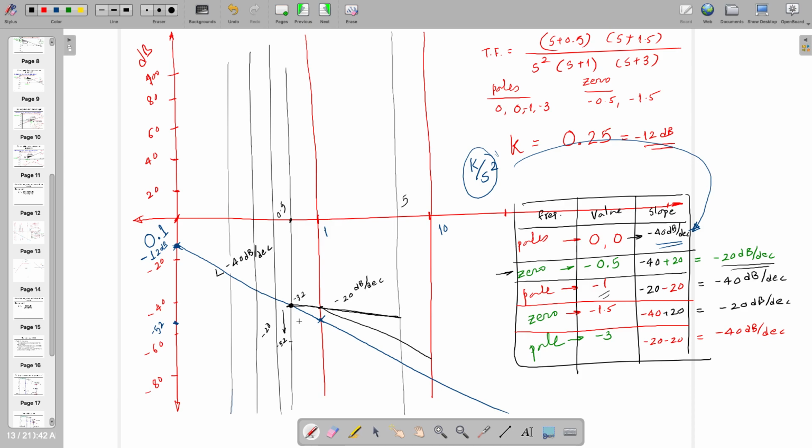I just wrote what he told. How will we calculate accurately? For my equation, you have to put 0.5 in this transfer function and find it out. If you want to find it out accurately, mathematically, you put omega equal to 0.5, replacing all the j omega.